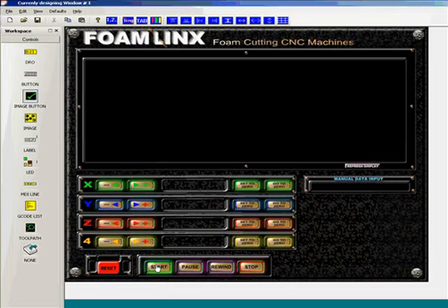You'll now notice that the button has become invisible except for this blue and green outline. That does not show in Mach itself, but it just gives you an idea of where the actual button is on the screen. Now a quick way to make lots of buttons is just click on the original one you've made, go up to edit, copy, and then just press Ctrl V a few times and you'll notice some more buttons appear. You can then assign them, then place them over the other buttons that you want to place on your screen. Now you'll remember that I've assigned the function of start, and so all of these buttons will be start until I change them.